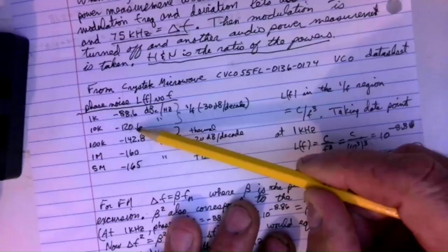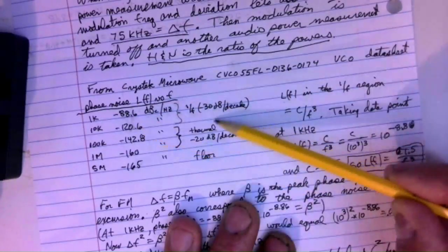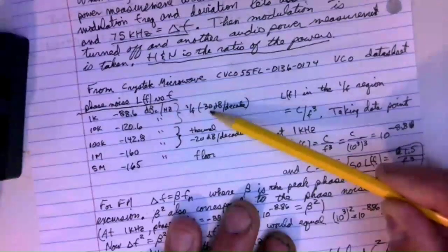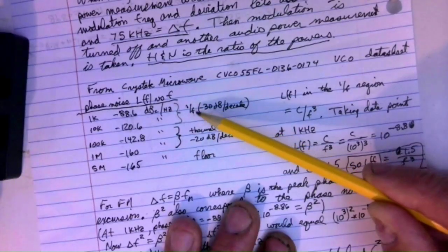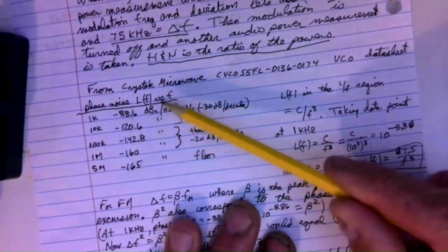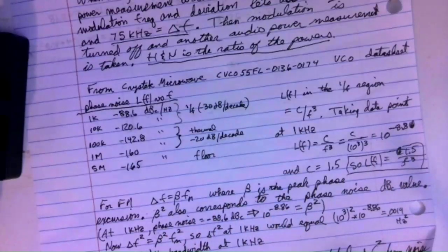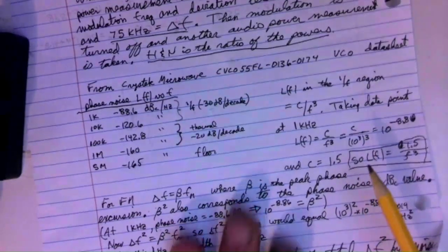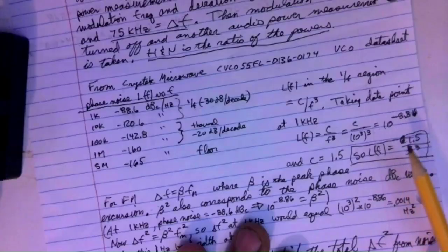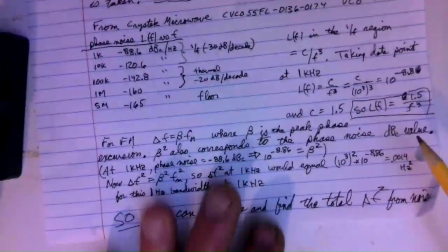Because this delta right here is a little bit more than 30 dB, and when you write this, you're assuming it's going to go exactly 30 dB per decade. All right, so now we have an expression for what L of F is in terms of F, and something we could integrate. And it's a real easy integral to do, so don't panic.